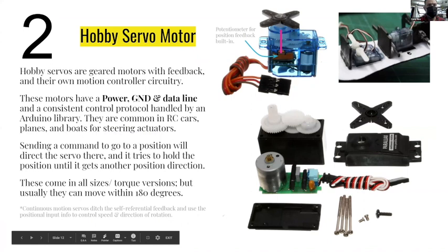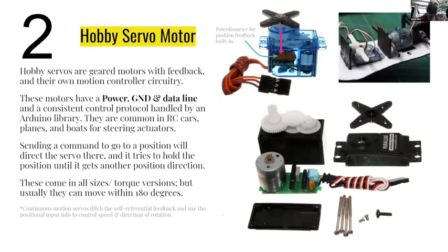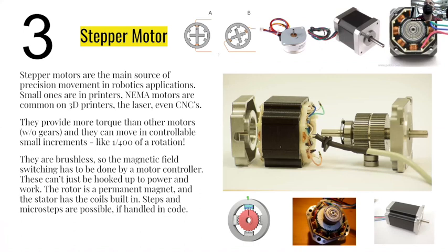And so servo motors, essentially they have 3 inputs: power, ground, and a data line. The data line is something that you have to choose a PWM pin for. They take a PWM input. Then there's stepper motors. Stepper motors are a different category of motor. These are next door neighbors to brushless DC motors. So they are a brushless DC motor, but they're not meant to spin continuously.